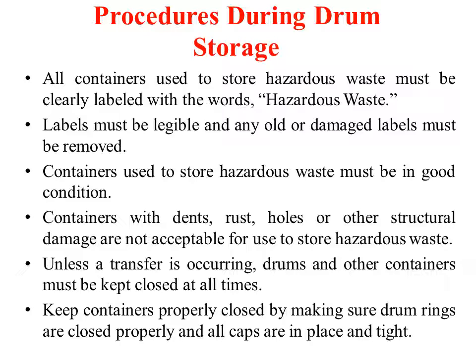Next, let's see what is the procedure for storing such drums. The first point is all containers used to store hazardous waste must be clearly labeled with the words hazardous waste. So a non-employee of that company, if he comes across a container, should know that this is hazardous. So proper labeling should be done, and it should be legible so that it can be properly read and understood, and any old or damaged labels should be removed.